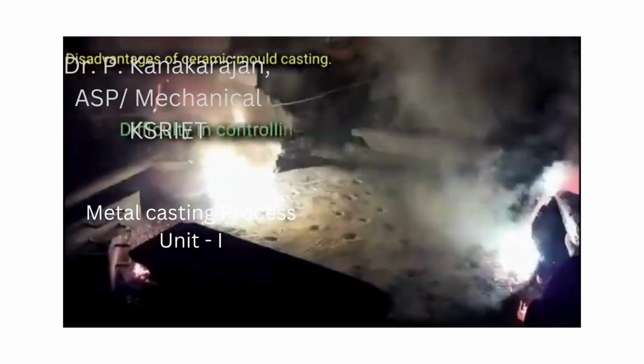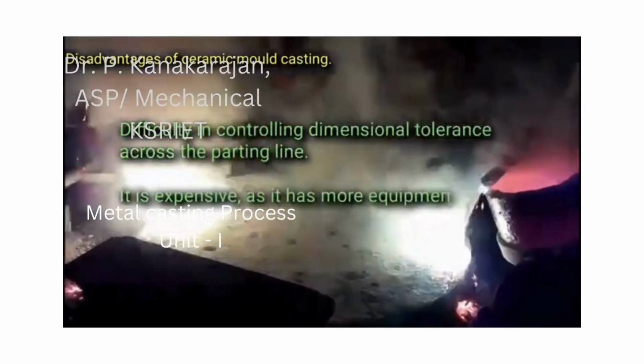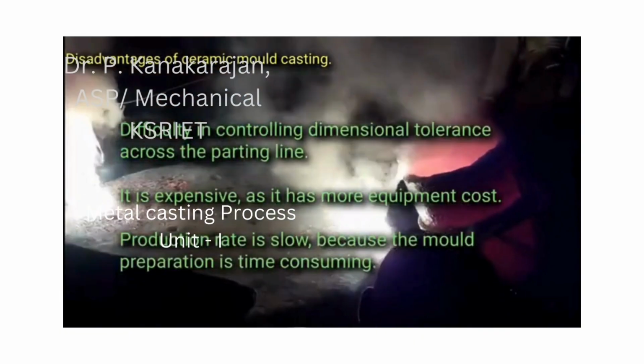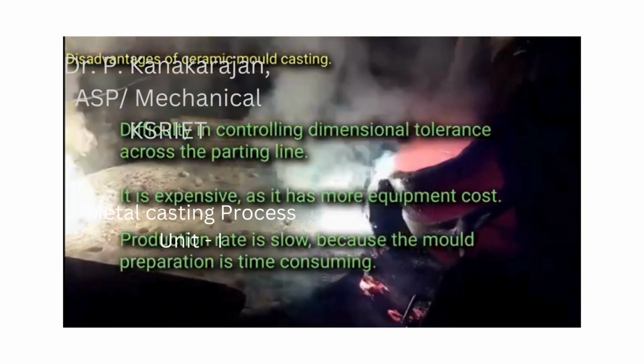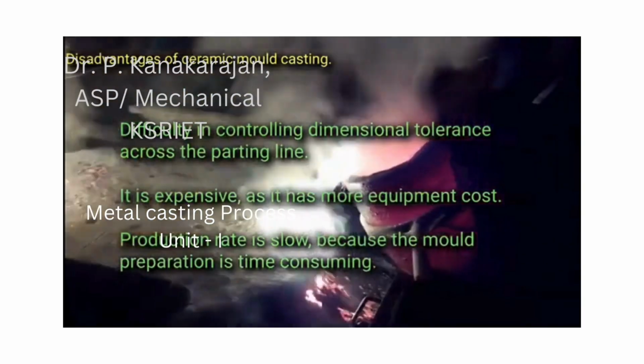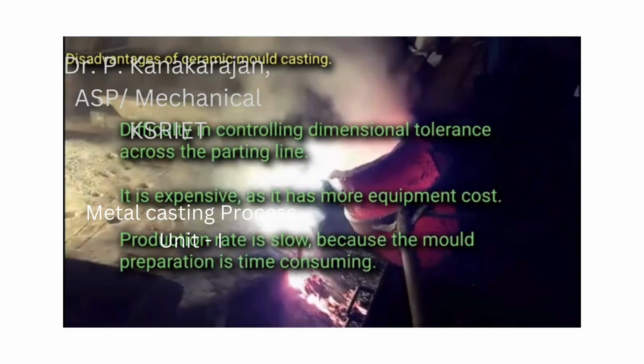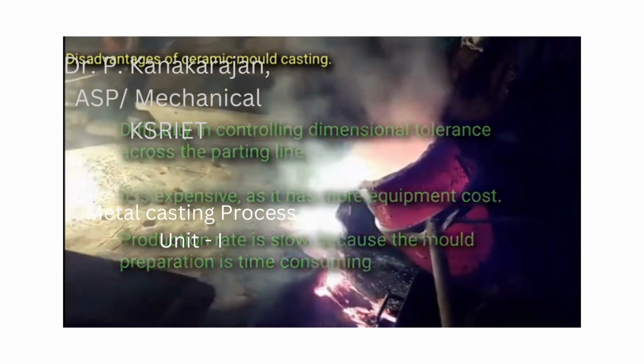Disadvantages of ceramics mold casting. Difficulty in controlling dimensional tolerance across the parting lines. It is expensive, as it has more equipment cost. Production rate is slow, because the mold preparation is time-consuming.